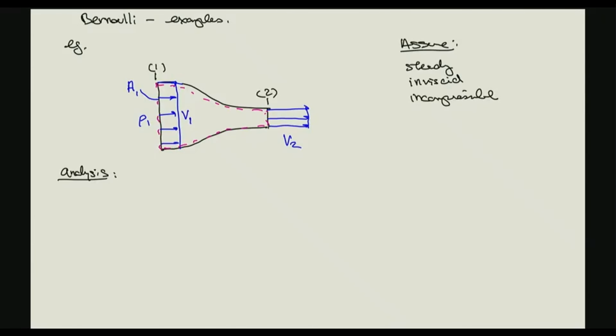But the standard procedure is, once you have a sketch of the flow and identify the known quantities, first you might apply conservation of mass, and then you might apply conservation of momentum. That's the standard procedure if you don't know what else to do. Conservation of mass, conservation of momentum.